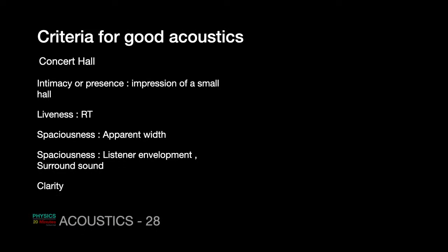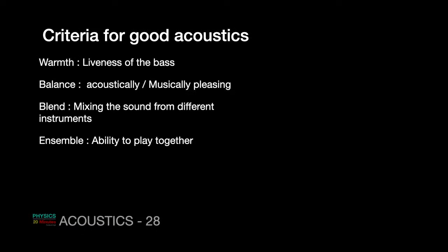Clarity, as we have already discussed: a longer reverberation time would lead to the loss of clarity. Music requires different things: warmth, liveliness of the bass, and balance between the left side and right side speakers. In an orchestra, the instruments kept on one side of the stage must balance with the musical instruments kept on the other side. It shouldn't happen that one side is overpowering the other. Blend, mixing the sound from different instruments suitably, is important.